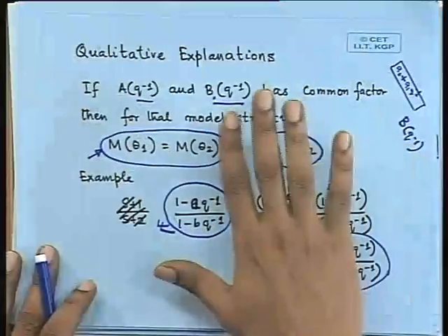So first of all, this is needed to make the problem non-unique, and we will see that this thing comes again and again. Even in the case of identification in closed loop, again we will encounter a situation where this parameterization will become non-unique. So first of all, the parameterization should be unique, such that there exists only one solution which fits the input output data under that structure of the model. So that is the first thing.